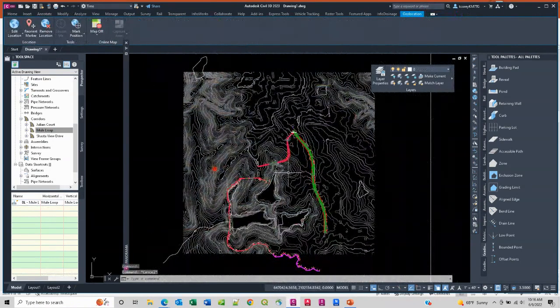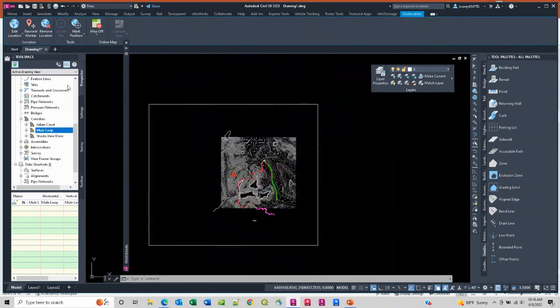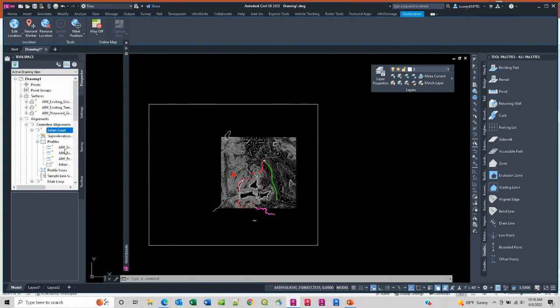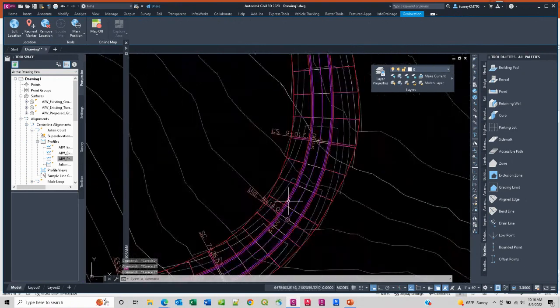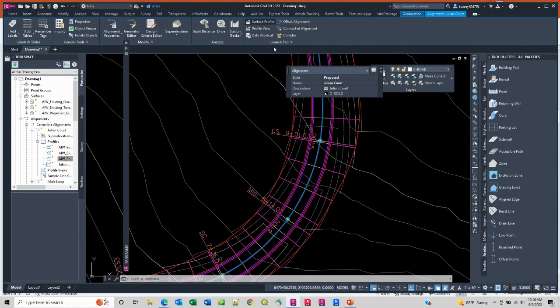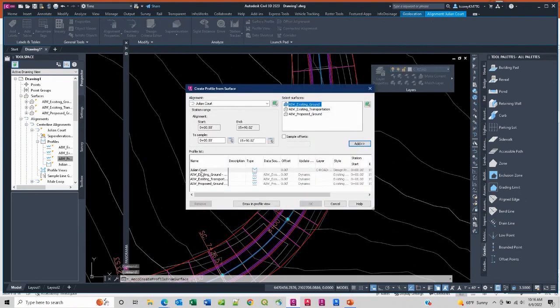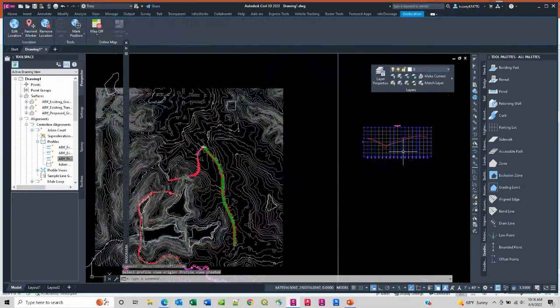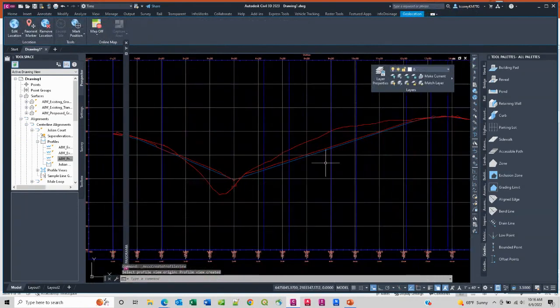All right, so we have the terrain, we have corridors to start, we have alignments. If I wanted to do profiles, the alignments have profiles. I just haven't yet drawn profile views for them. Okay, so let's say I get this guy here, alignment, and a surface profile. You know, and let's just draw in view. I can very quickly get to laying out my design profiles.